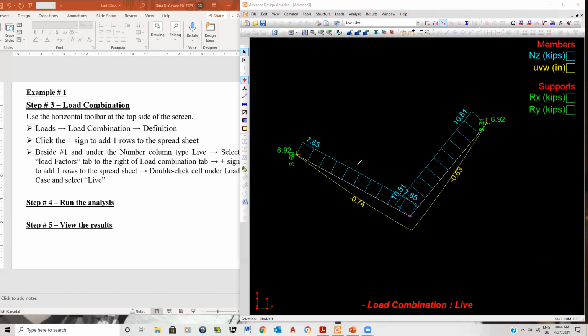Okay, so that's axial forces. And like I said, bending forces. Well, that's what happens when you have a bending force. What happens in that case? This is in tension, this is in compression, this is in tension, and therefore the fibers here act differently, and so on. And a shear force, again, acts on the fibers in a different way, and therefore bending resistance, shear resistance, tensile resistance, compression resistance. This is all going to depend on whether those forces are present, and if you have to evaluate for them. That's all it is.